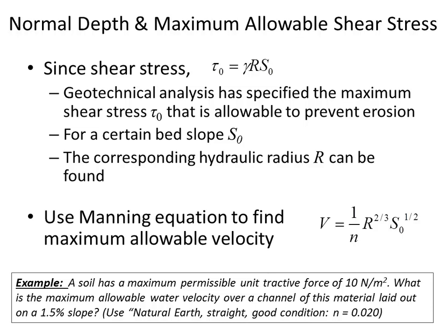Based on the geotechnical analysis, any water velocity that's greater than that is going to exert a greater shear stress and could cause the stream to scour.